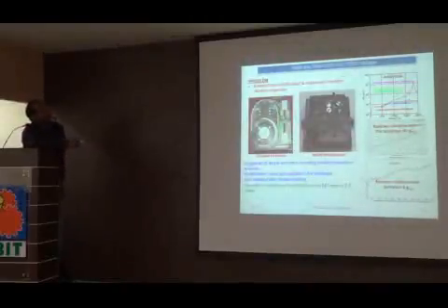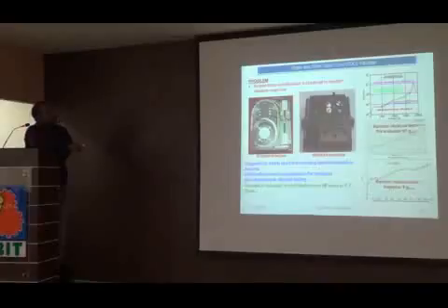And there are a few other cases, like say one of the IF4G, which is a fiber optic system. This is again an electronic package where at the initial design stage itself we found that the response was very high. It was coming to more than 16 times the input. More than 2 to 3 times the input was not allowed.